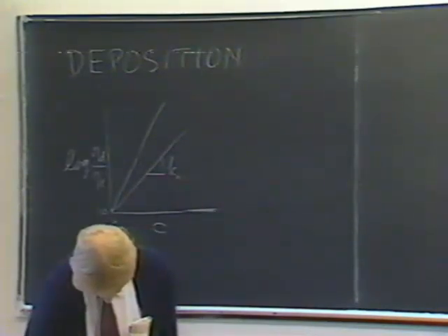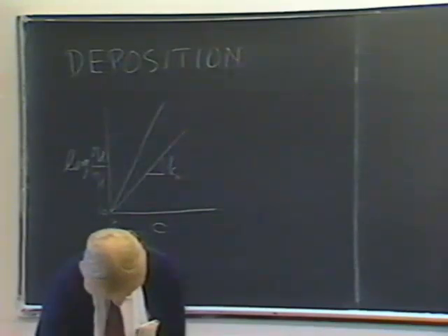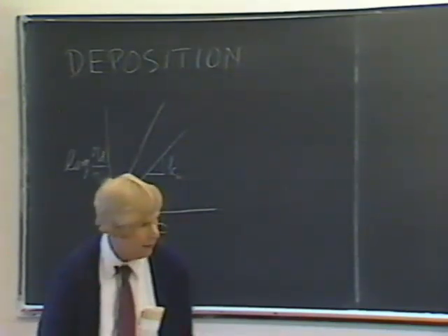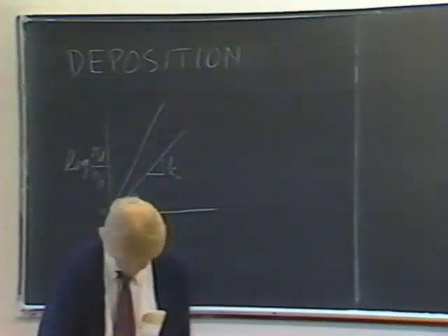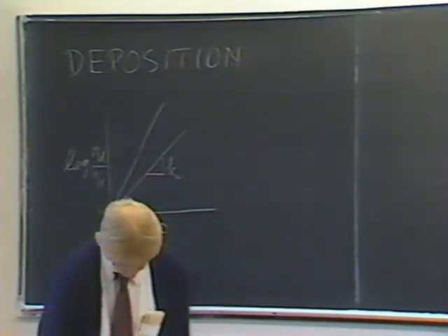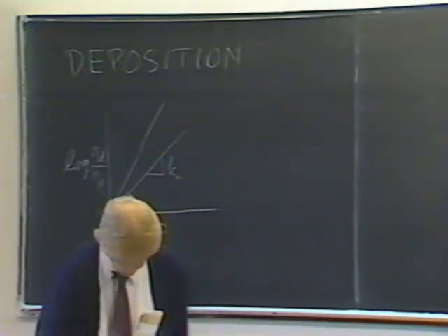Now there's two things that are happening there. One is the crushing that we just discussed, and the other is that the material is gelling. That is, it's changing its structure so that it's a more uniform structure, but still one that falls off linearly. On the next page, there's some more plots for much later times, and you can see there's no knee, no bend in those curves.